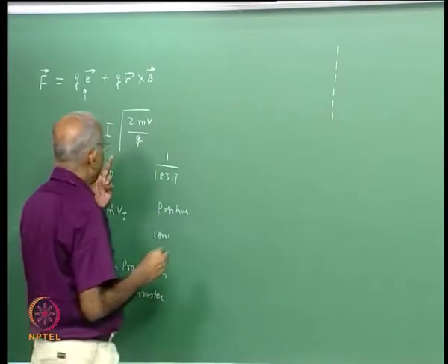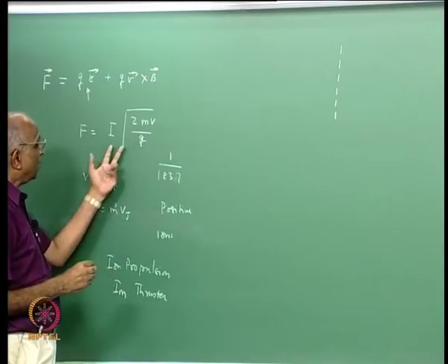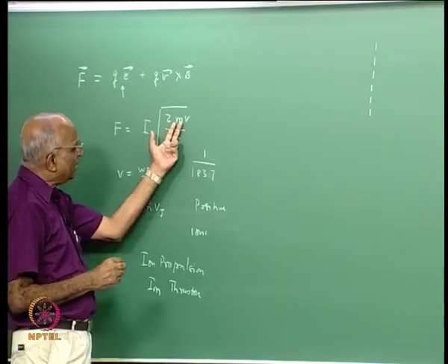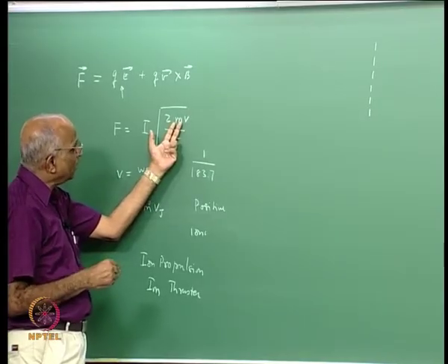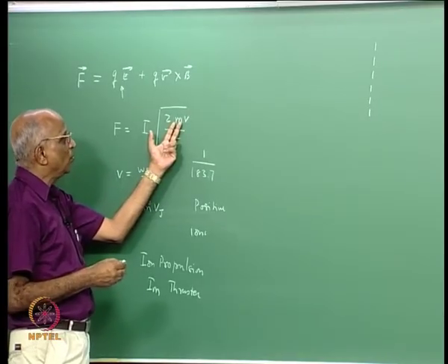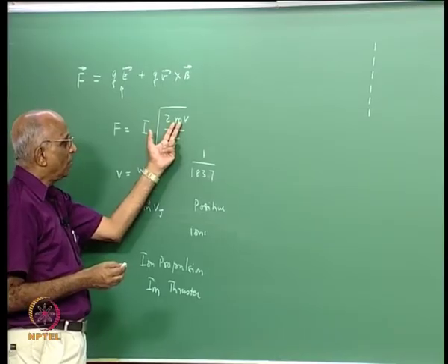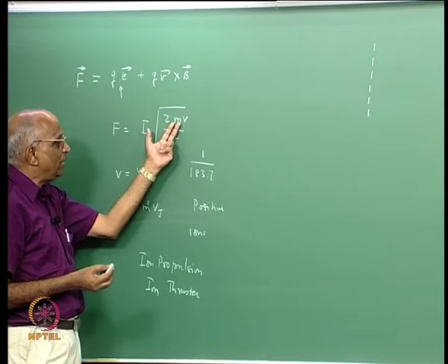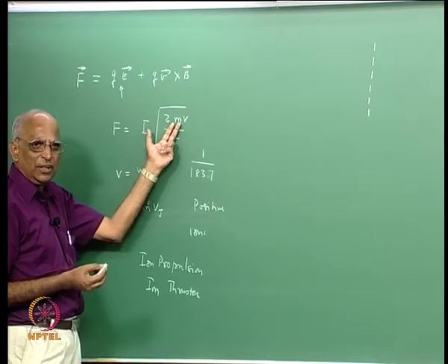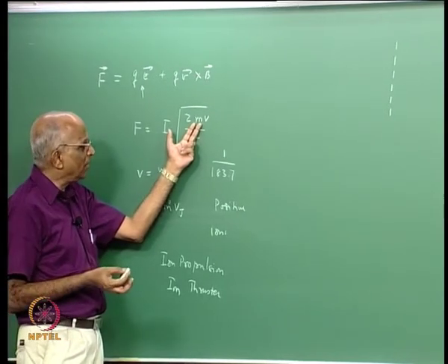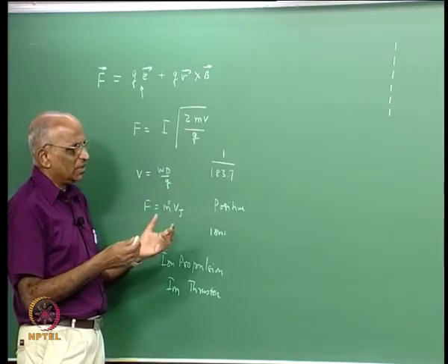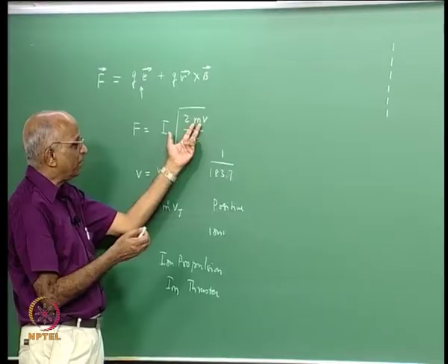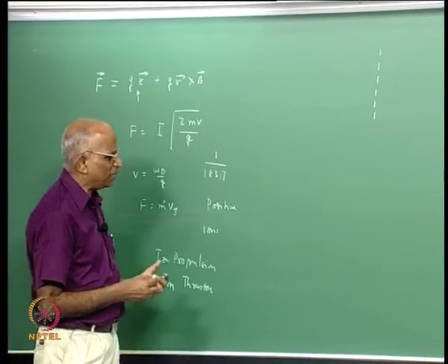Having said that, we also went one step further and said if I have to use this electrostatic principle and generate an ion rocket, now I call it an ion rocket because I am going to use positive charges. We said we would also like to have substances whose molecular mass or atomic mass is larger, and therefore I would rather have heavy substances like maybe mercury, maybe cesium, maybe xenon. Mercury we said contaminates the surfaces of a spacecraft.